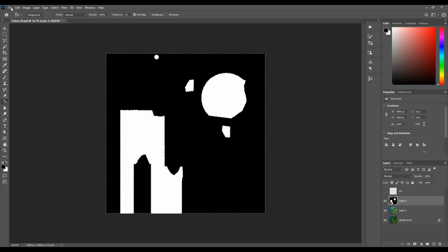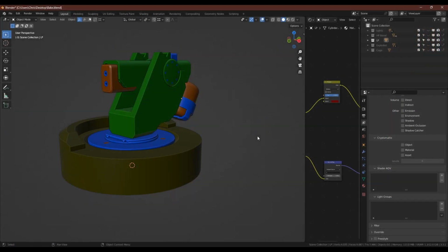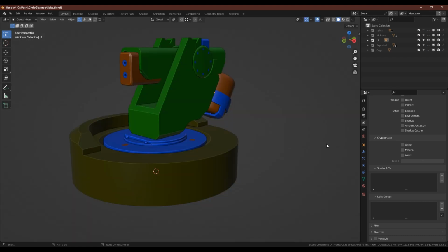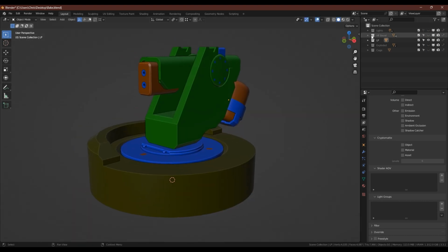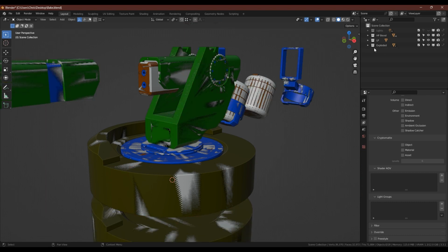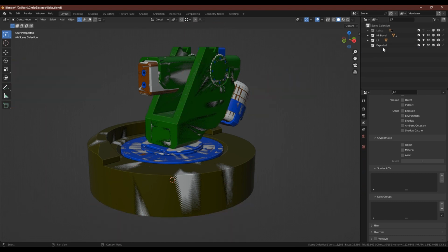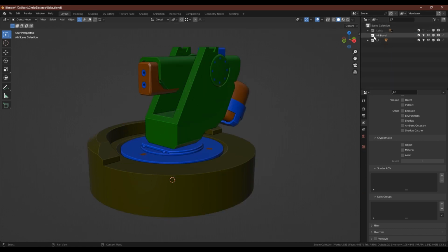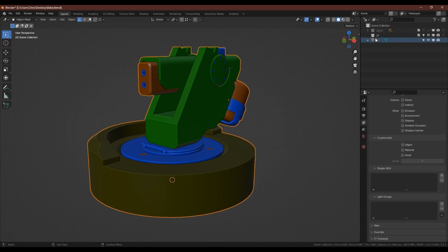Now moving on, we want to clean up the last blend file that we've got. So we're going to basically delete out everything apart from the low poly model. So if I just show all these collections, we can expand the cage, delete the cage and its collection. Same with the exploded part. Same with all of the high poly. And the reason we're doing this is basically to make it nice and light so that we can procedurally texture it without the file being too overbloated.